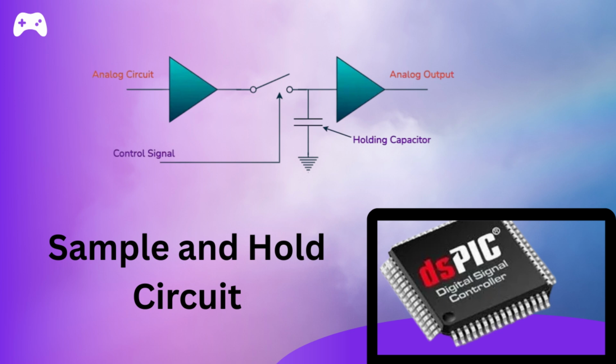If there is a large input impedance from the signal, then this analog holding circuit will take more time to charge. So in that case, one has to put an amplifier on the analog signal so that the input impedance to charge the holding capacitor is less, and then measurement accuracy is maintained. So while designing the ADC, one should take care of the input impedance of the sensor circuit or the circuit which supplies the analog voltage.